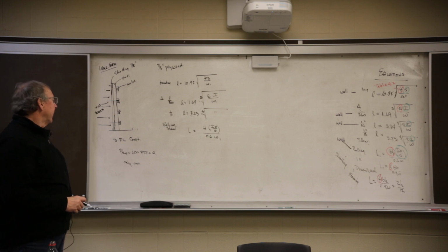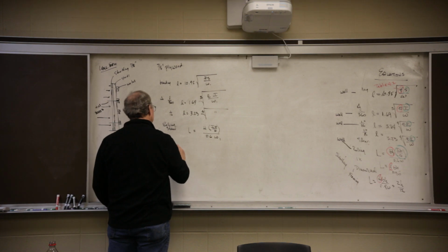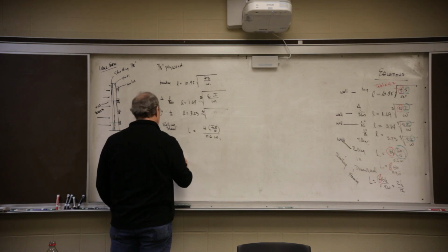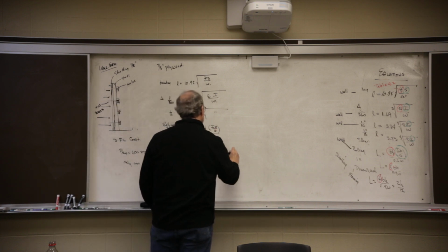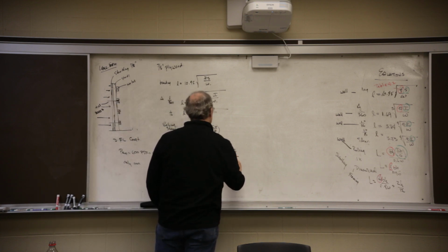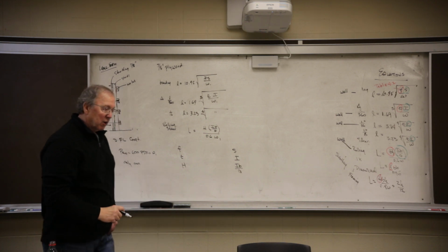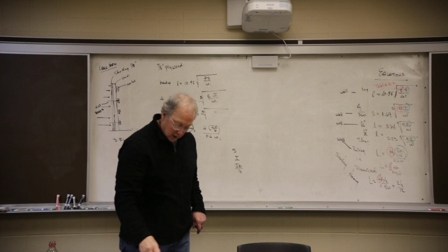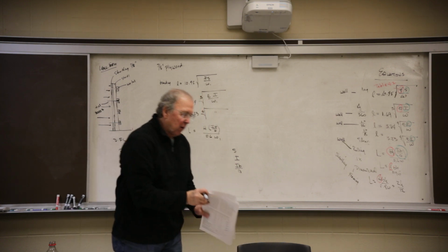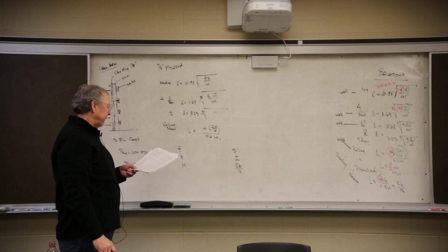Do exactly the same as we have. Unfortunately, I don't have any of the data, so let's get it. Plywood, what do I need? I need F, E, H. I need S, I, and IB over Q. Go to table 4-2 on page 4-5 and go down to the plywood area, the very bottom.